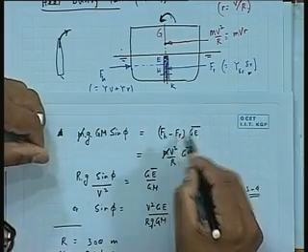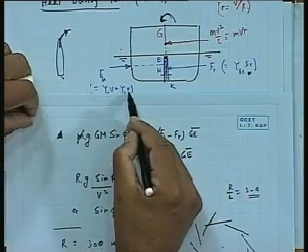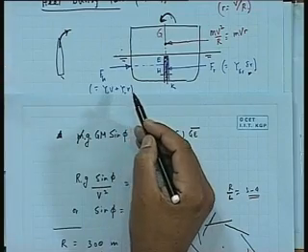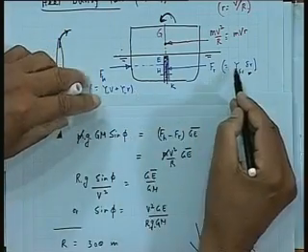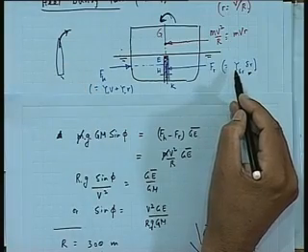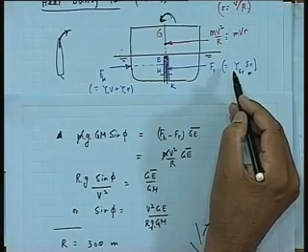So this will go to 0, but at the same time the speed V and R will not come to 0 because the ship is moving. So this will still remain almost as much, but this will suddenly go to 0. You are going to bring the rudder back to 0 in say 5 seconds. Normally 3 or 4 degrees per second. But velocity has not come down, as you know, ship, you know much more than me, it will take a long time. So suddenly you are reducing this to 0.